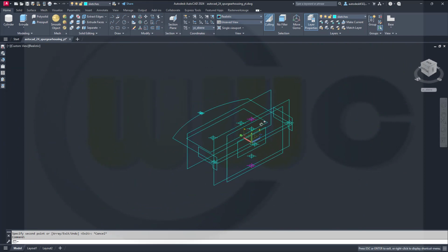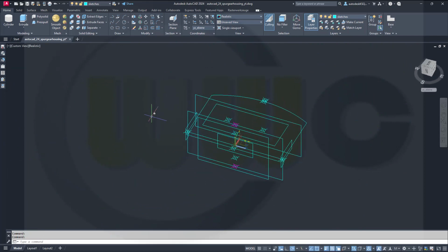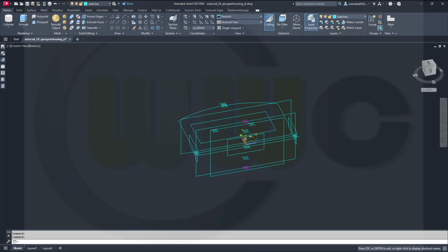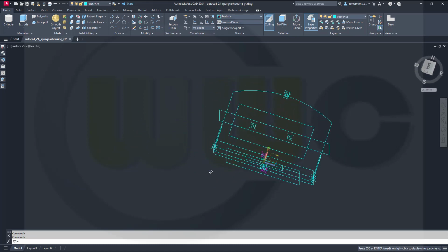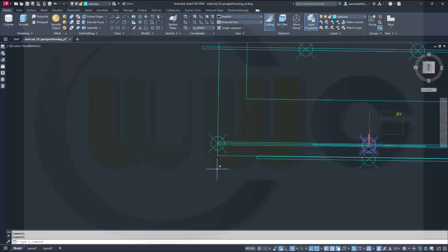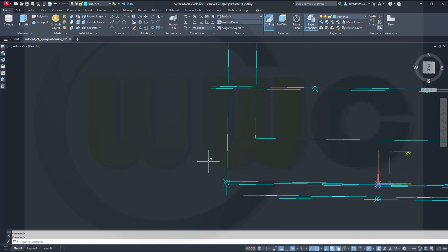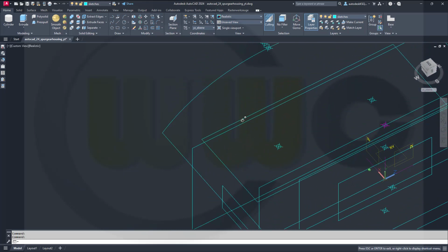Now let's make an extrude in that direction and this direction. And of course there is a draft, so I want to go for, let's say, 5. What's the thickness of that housing? So let's go for 3, move it 1 millimeter to the other side. That should do the trick.